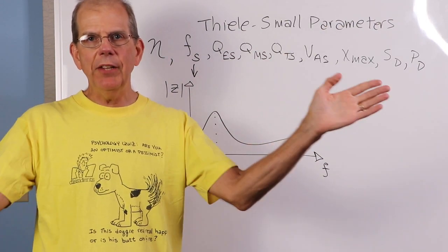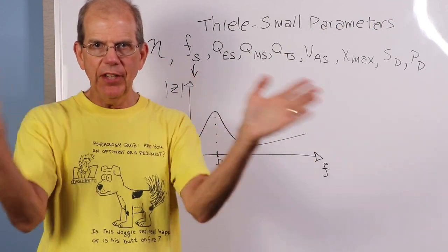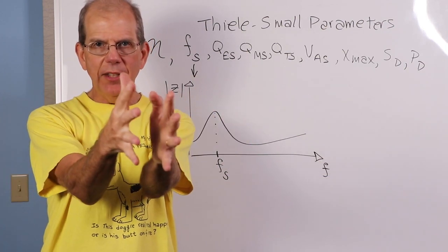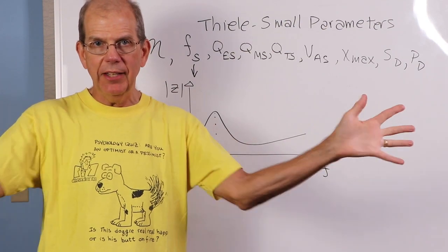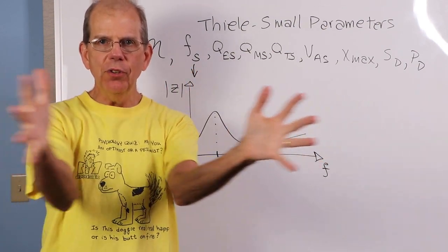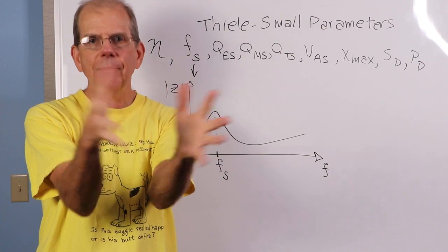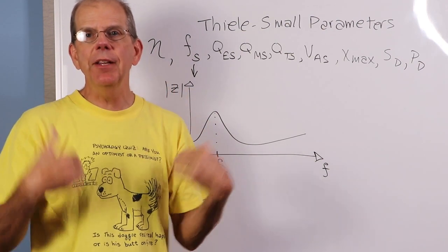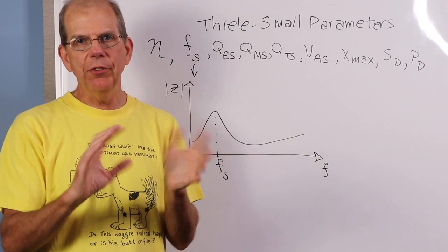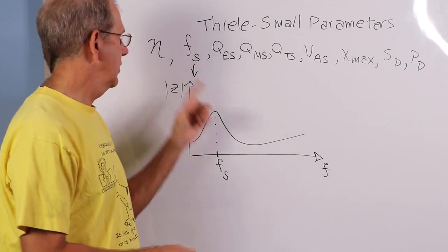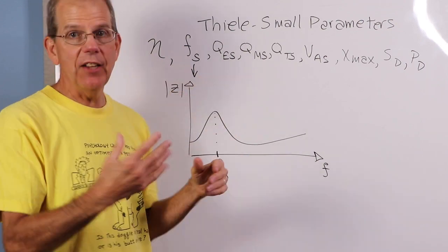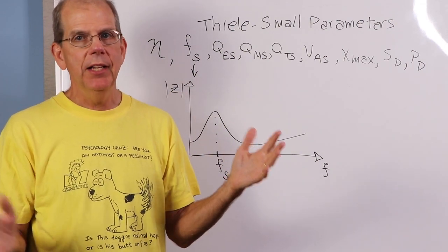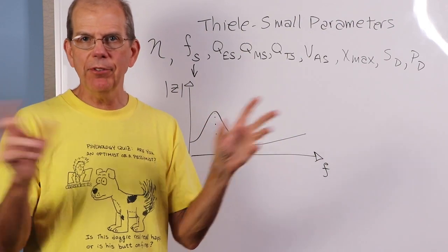Now, you can come up with ways of focusing the sound. For example, using a horn or a line array, you can sort of focus the sound in, kind of like a garden hose. Instead of being like this, it's like this. Well, if you can bring it together, focus it, you can get a higher sensitivity for the same efficiency. So although there is a correlation, in other words, speakers that tend to have high efficiency also tend to have high sensitivity, it doesn't have to be that way. Again, we want an apples to apples comparison.